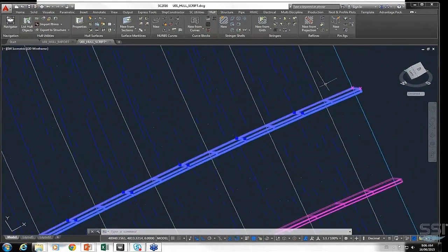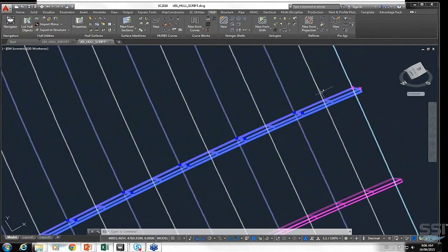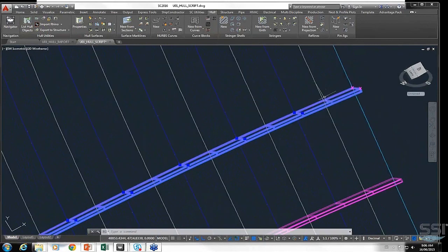Oh, remember when I told you about the control sections and the visible points? What you can see here is there are these blue squares and these pink X's. The blue squares only show up on a control section point. So you'll notice that this is a visible point, the white one, and the blue line there is a control section.